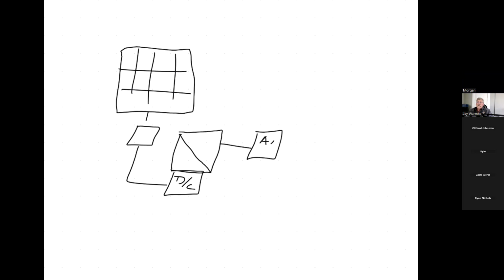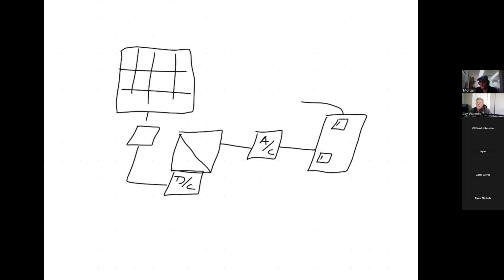And from the AC disconnect, in a very small residential system, you're typically going to go into a service panel. You're going to go into this breaker, and then you've got your main breaker. And from the main, it goes out to the meter. And then from the meter, you go up to the transformer, normally again on the telephone pole. So this would be a very simple grid-tied system, all the different components, what they do.